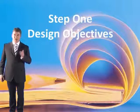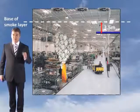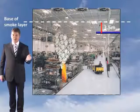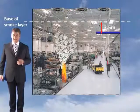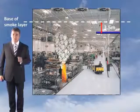Let's go through the exercise then using the 11-step method. Step 1 is your design objective. Now this is specified as life safety, and it's specifically to maintain a clear layer height above the mezzanine. In this case it's been decided to maintain a 3.5 metre clear layer height above the mezzanine. Usually it's only 2.5 metres for staff, but in this particular circumstance it's to maintain a clear layer height 3.5 metres above the mezzanine, as you can see here. So that was step 1.